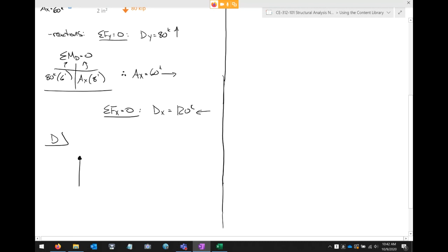We've got a vertical member. Well, let me move this over so I'm not crunching here. All right. You got a vertical member, but we said that's a zero force member. You've got a horizontal member, but we had already figured out that that's 60 kips in tension. You've got a horizontal reaction that's 120 kips, and you've got a vertical reaction that's 80 kips. All right. And then we got this diagonal member. Well, I propose that has to be 80 kips going down.